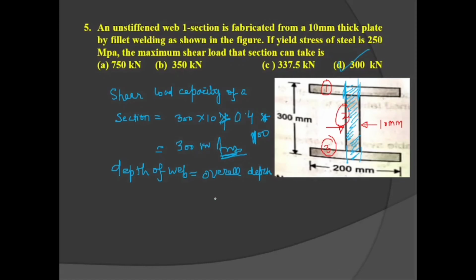Option D is correct. Depth of web is equal to overall depth, because most of the shear force is taken by the web only. That's why for all the calculation purposes, depth of web is equal to the overall depth. Okay, now let's move towards question number 6.